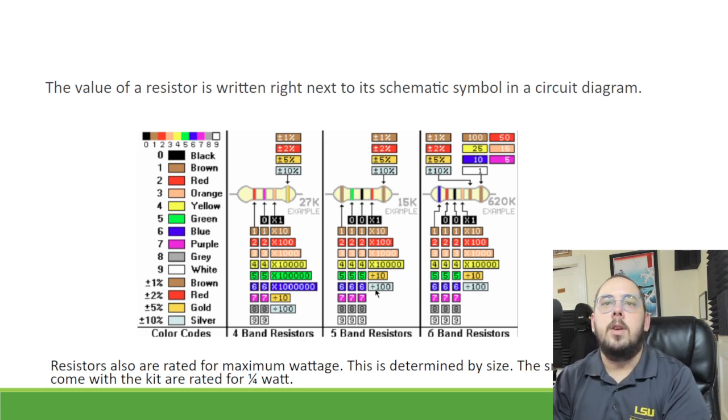Last one, again just going through the process, we've got here 620 kilo ohms. So the blue is 6 for the first one. Cool. The second one is red, 2, 6, 2. 0 is black. 62 times 1,000, orange.